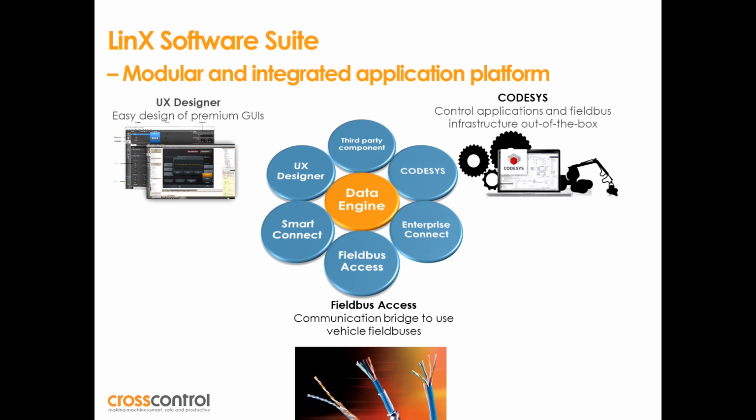Codesys contains already out of the box fieldbus functionality with, for example, J1939, Modbus and Profibus, Profinet, and I think maybe 10 more different field buses.